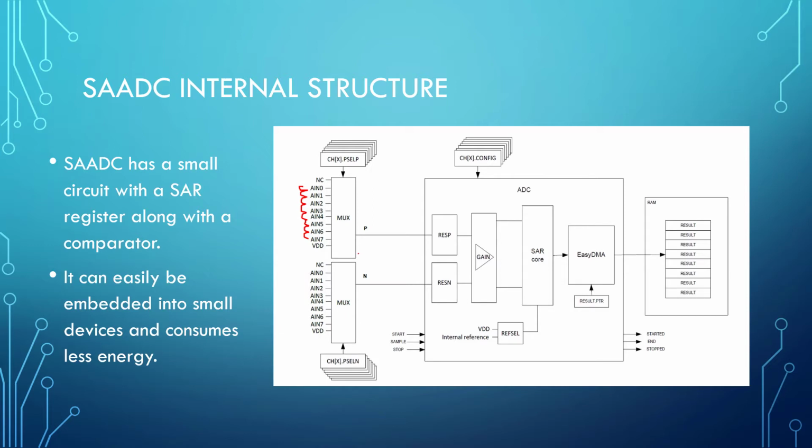If we are using 2 channel inputs, then we will be using the ADC in differential mode. If we are just using 1 channel, for example the positive channel, the P channel, and we are not using the negative channel, then what happens is this channel is internally grounded. So we don't have to worry about this, and we can just easily read the voltage level on the pin.